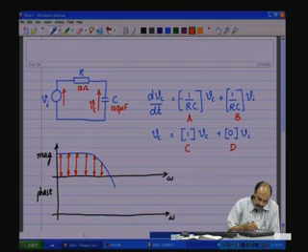So, almost all circuits will act as a filter in the sense that they give different gains at different frequencies. So, the gains change as the frequency changes, and that gives you a sense of the behavior for harmonics. So, for harmonics, what is the kind of output that you would get if there is distortion or a non-sinusoidal waveform or different frequencies at the input.